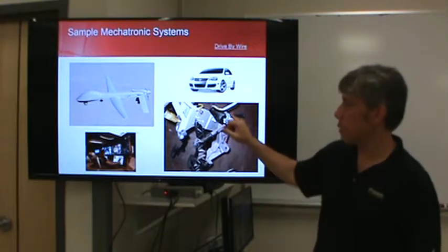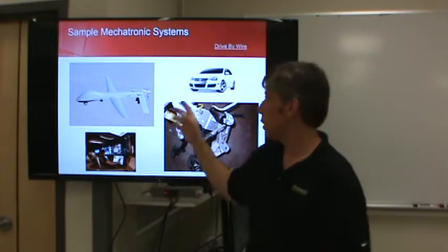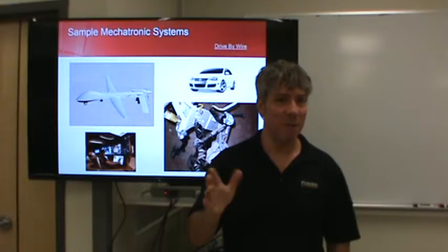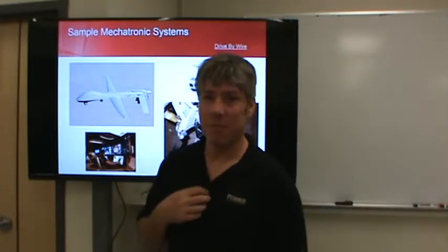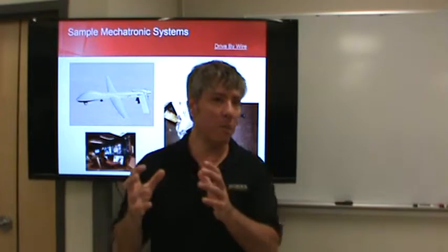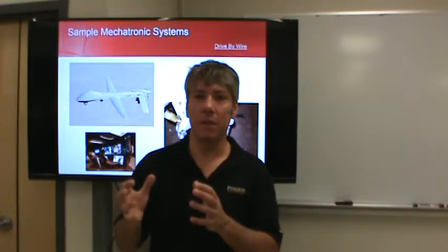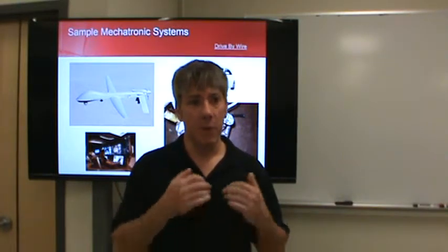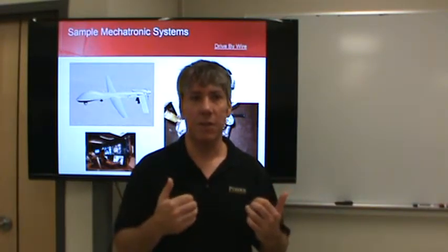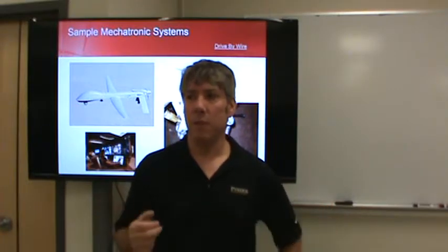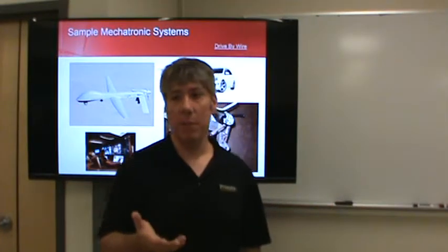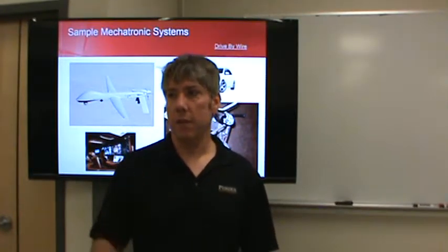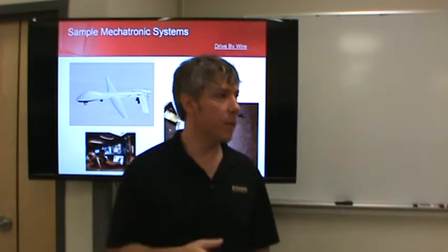The fact that makes it mechatronic is that there is an injector pump on these cars, and by the way, I shouldn't make recommendations on camera, but I don't really recommend the Jetta, okay? I drive one because I rebuilt the engine in it, but there's an injector pump that costs about $1,000 to rebuild, and you need to rebuild it about every 100,000 miles, or it locks up, takes the timing belt out with it, destroys the head, impacts the cylinders, and now you've got a big expensive mess on your hands. Okay, that actually happened in my car. The injector pump locked up. That's why I know about it.